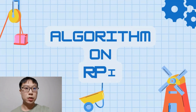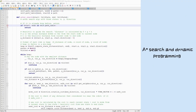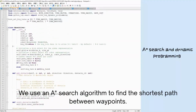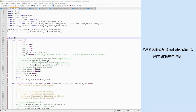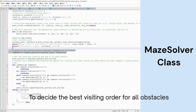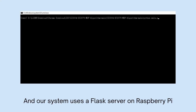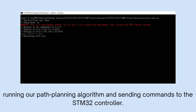Hi, I'm Yizhe. I will continue to talk about how we implemented the algorithm on the RPi. We use an A-star search algorithm to find the shortest path between waypoints. To decide the best visiting order for all obstacles, we applied dynamic programming, solving a version of the traveling salesman problem. And our system uses a Flask server on the RPi running our path planning algorithm and sending commands to the STM32 controller.